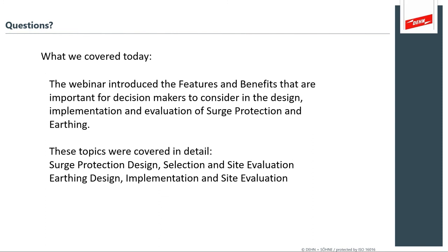I would just like to address this last question addressing maintenance on SPDs. The person is asking, what type of maintenance schedule should he put in place for the surge protection devices he has installed? So SPDs generally do not last forever. Metal oxide varistors do degrade over time, and it's sort of a double question. How often are you being struck by lightning? How often are you experiencing problems on your site?